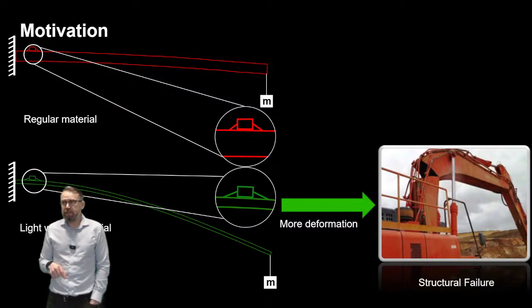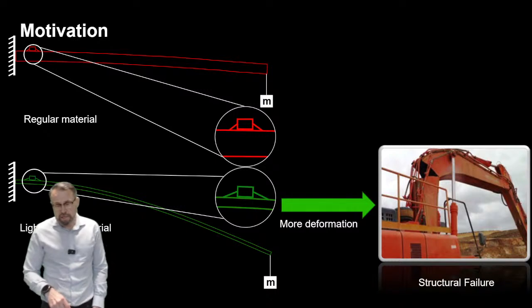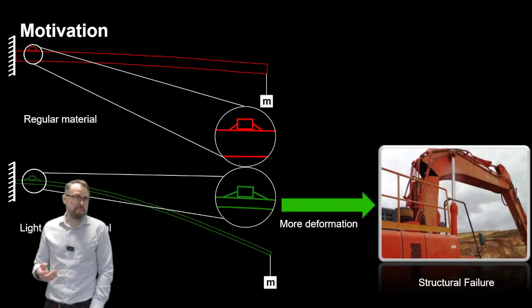As can be seen here in a cantilever beam, you can make the structures more slender, and you can handle the same amount of mass when using high-strength steel compared to conventional steel. Now, as you can see, in the cantilever beam that is green in color, deformation becomes more significant, and the dynamic behavior becomes more cumbersome to deal with.